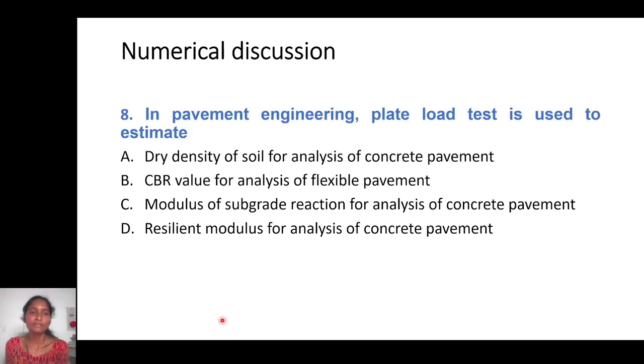Next question: in pavement engineering, the plate load test is used to estimate what? Why do you need to do the plate load test? Let's start from the first: dry density of soil for analysis of concrete pavement. They are saying that for concrete pavements, if you want to determine the dry density, we need to do the plate load test. But when we did the plate load test, did we determine any dry density? We already have the core cutter and sand replacement methods for determining the dry density of subgrade soils. So obviously it must not be that.